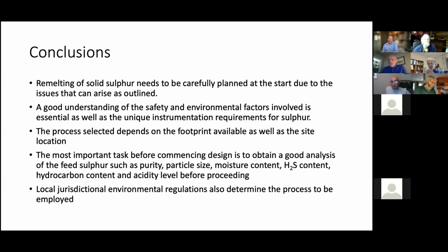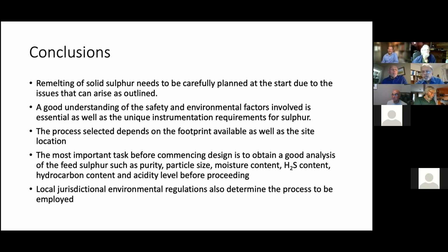Yeah, because as you say, it contracts by what, 6 or 8% or something like that as it goes. 13%, yes. Well, it sure made a big mess, because when it expanded, it burst the walls of the pipe. And because the pipe was insulated, you couldn't see where it had burst. Correct. Very good point. Thanks for raising that. Like I said, there's a major 22-mile pipeline in the Middle East that burst for the very same reason too.